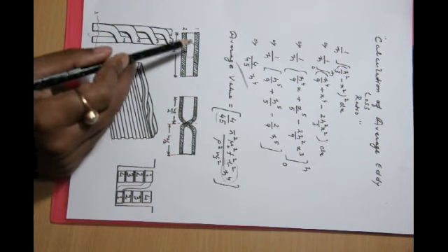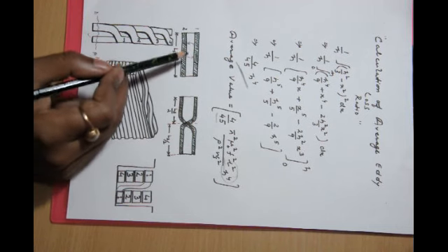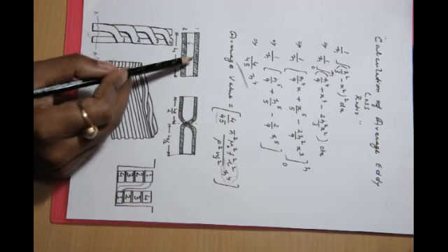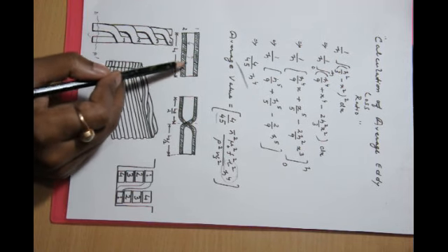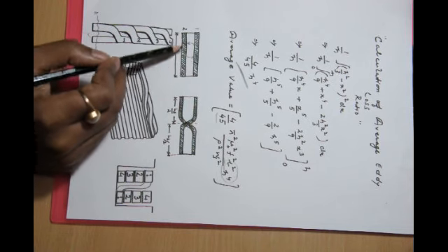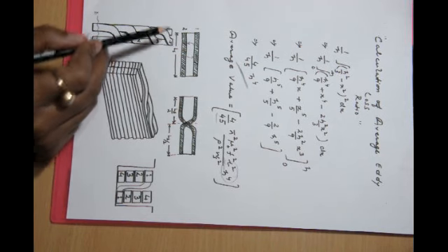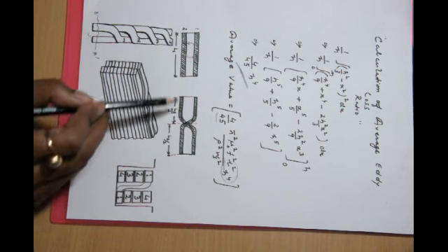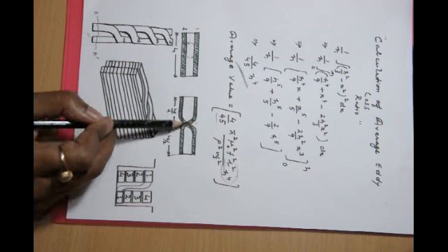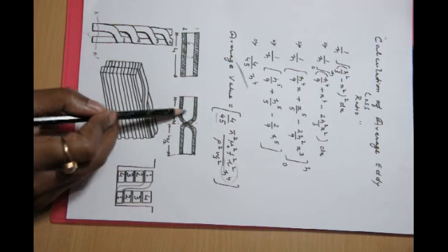Option 2 is to transpose the conductor. What will happen if you transpose it? Now see, just two conductors placed in a slot, there will be a difference in EMF because they occupy two different positions. This difference in EMF would drive a current which will result in losses. Instead of aligning the conductors like this, we reroute the conductor. We route the conductor like this, so that the difference in EMF between the two is minimum.